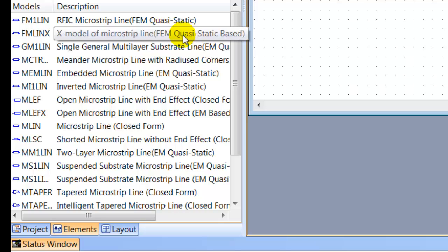It's pretty fast and it's very accurate so long as your line width is greater than a skin depth. Well, is that true? Yes, if you're on a board. The skin depth of copper at 1 gigahertz is 2 microns or so, and your lines are much thicker than that. The only people that might need to worry about that assumption would be people working on silicon chips.